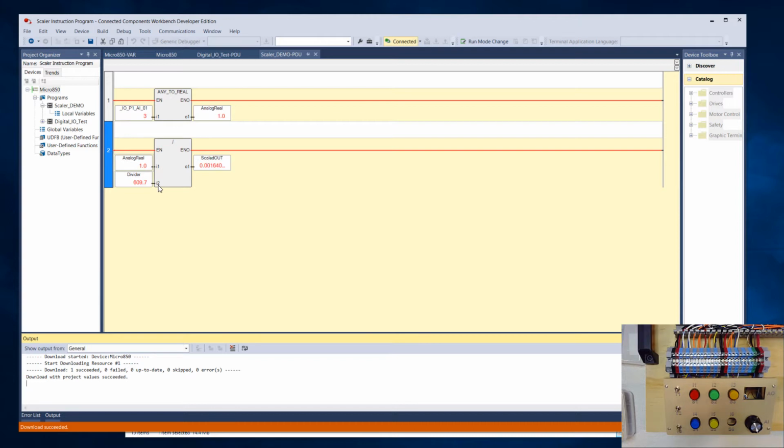You can totally do that with math instructions. It just takes a lot more math instructions, right? You have to create an offset so that you're not at 0 for your low end anymore. You need to have a scaling factor, and then also a divisor like we did here to limit your top end output at 45. So very doable, but we don't have to do it in this case because there's a built-in instruction that allows us to do that.